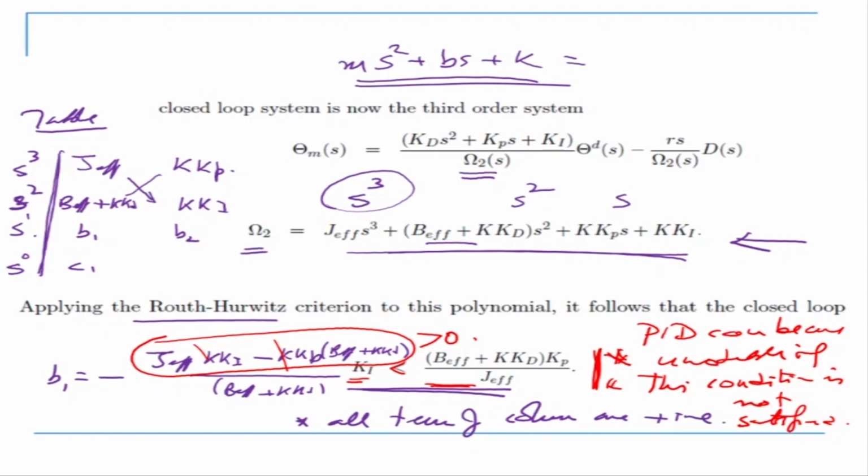So today we talked about the design of a PD controller and a PID controller, and we saw that when we write our full equation with the motor on the left hand side, and the input voltage on the right minus the disturbance torque, then we design the controllers, either PD or PID, put it inside the input voltage we give to the system, then study the stability and see if the system is stable.